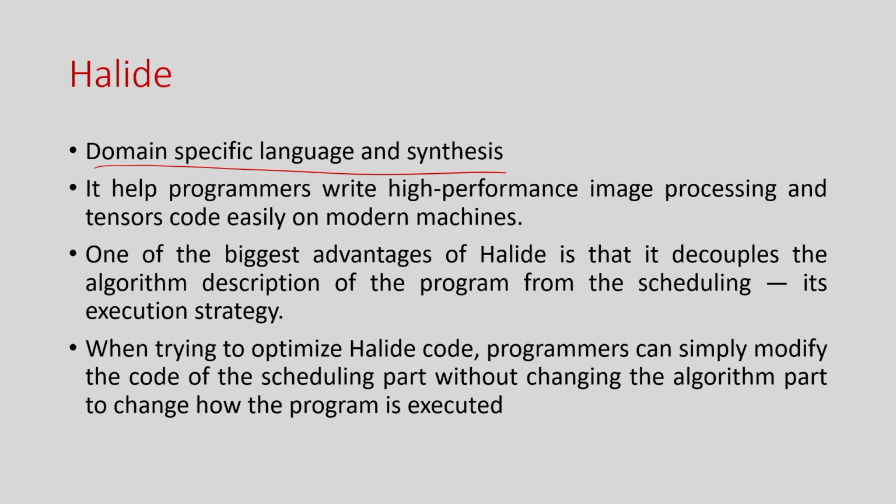Okay. But here the problem, as we have already discussed in this course, is that once you try to synthesize this application for efficient hardware, you have to manually modify the code, and not just a little bit, or maybe you have to try different ways. Sometimes you do loop reordering, loop splitting, loop interchange, and many other kinds of loop optimization.